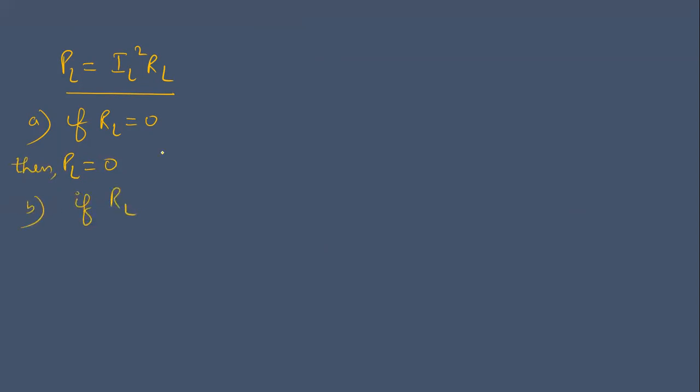Because the load power is equal to IL square into RL. So if you see here, let us apply two extreme conditions. One is if RL is 0, then PL is 0, right? The other condition is if RL is infinite, then IL is 0, hence PL is 0.